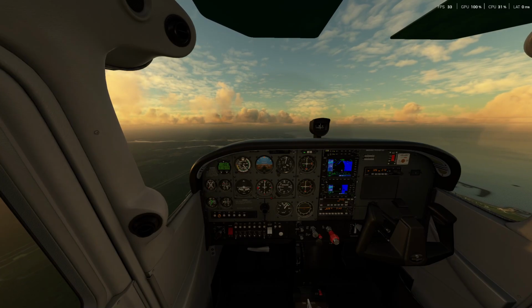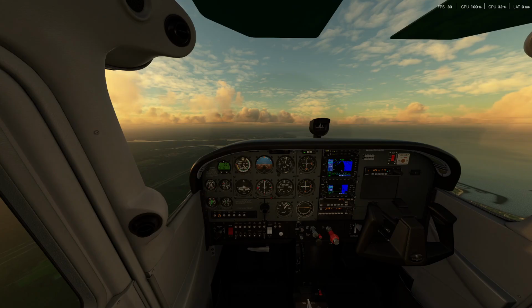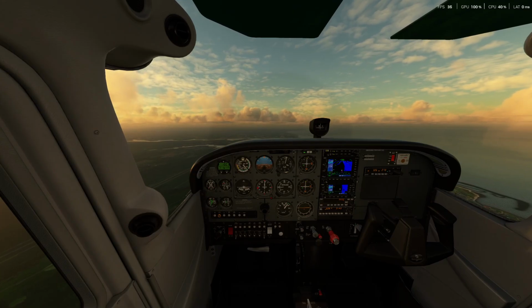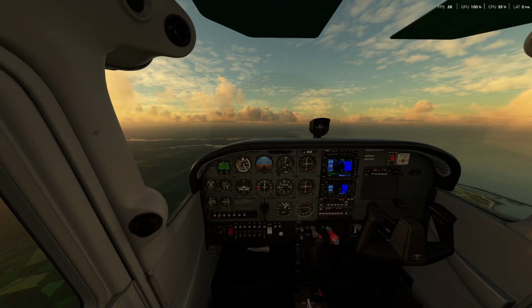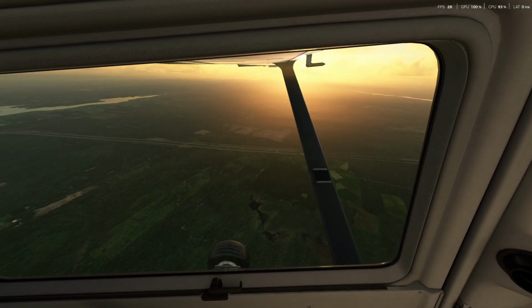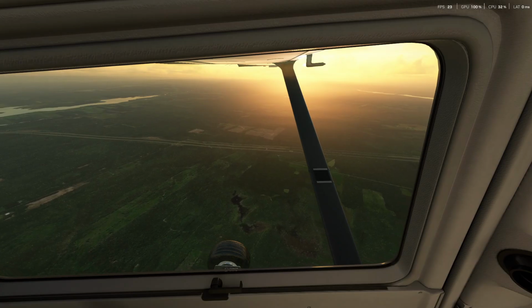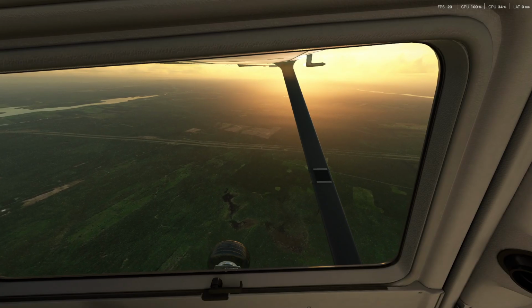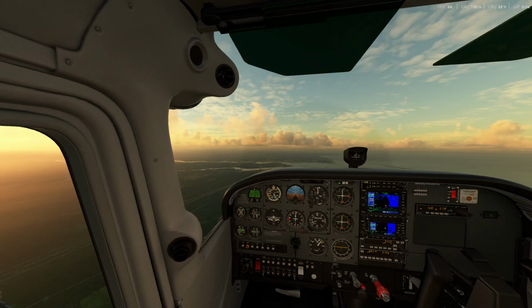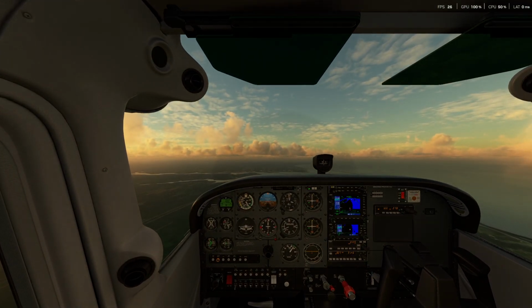So pretty much with this attitude here, your RPMs are set at 2300 and they're trimmed out to basically straight and level. And again, you can check the left and right and get a reference of where your wings are in relation to the horizon.